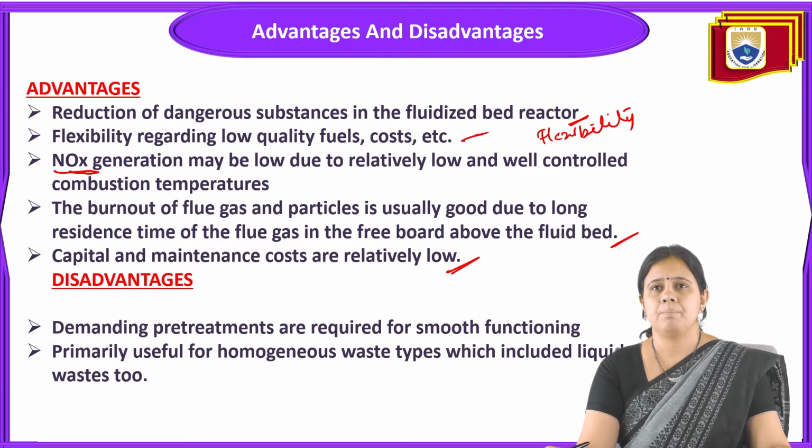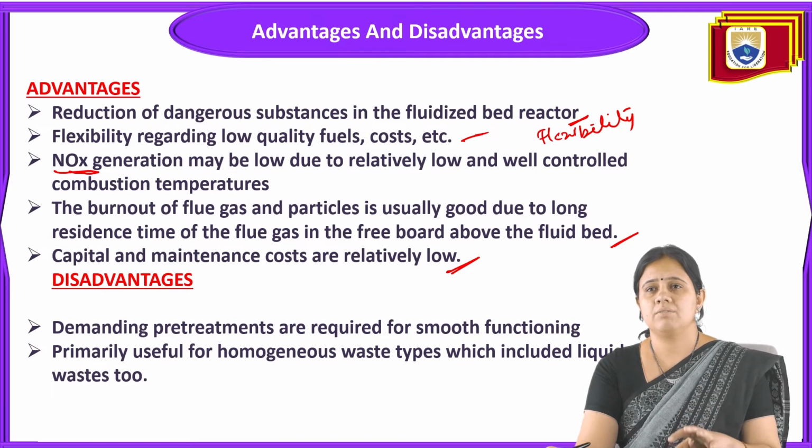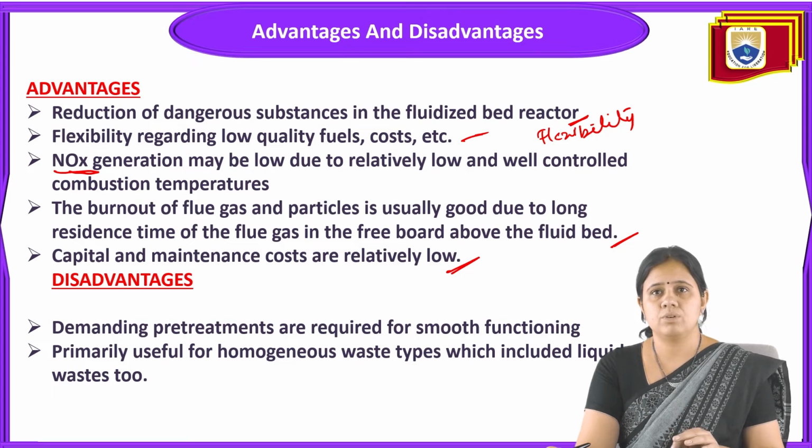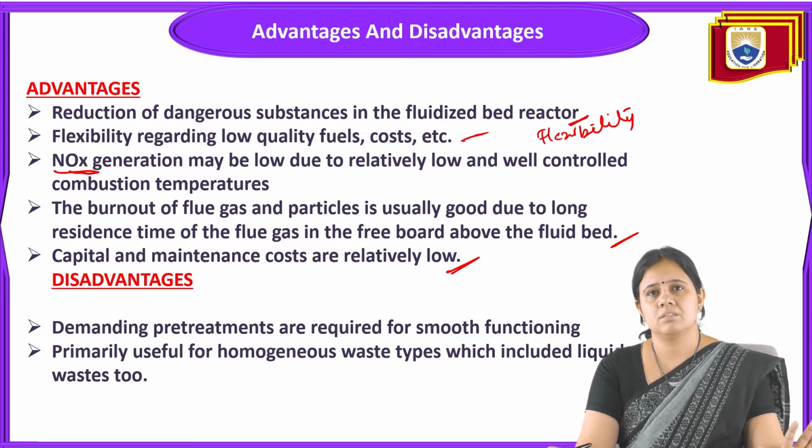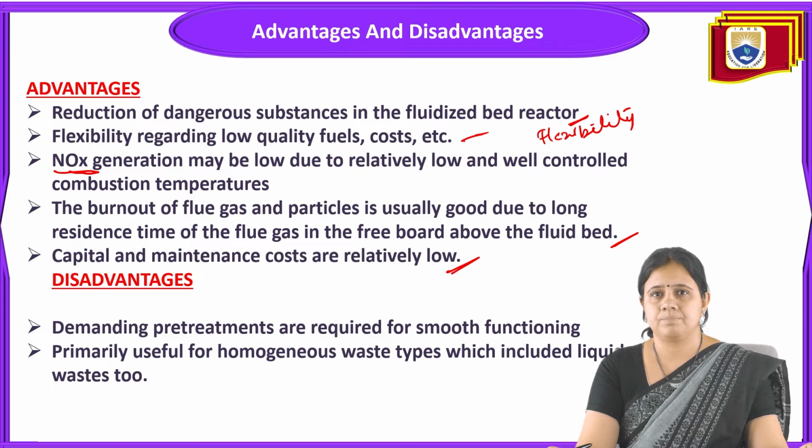NOx generation is low because of the relatively low and well controlled combustion chamber. The burnout of flue gas and particles is usually good due to the long residence time of the flue gas in the free board above the fluid bed. Capital and maintenance cost is low. So these are the 5 points that are the benefits of this fluidized bed incinerator.